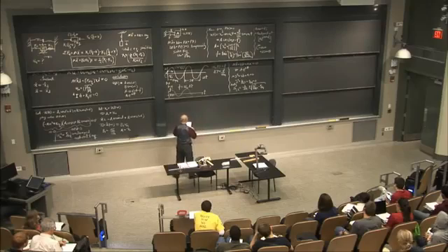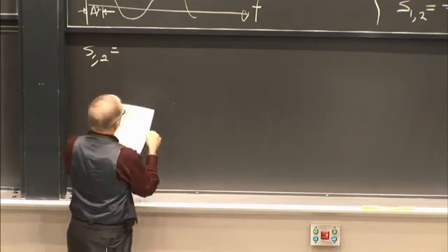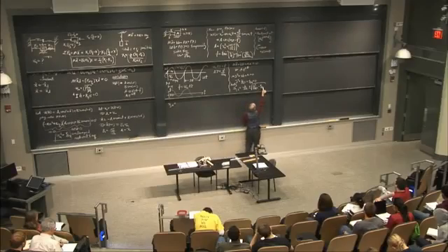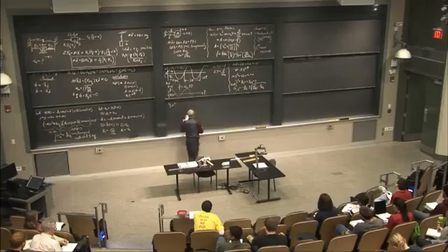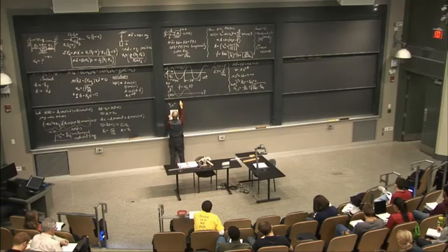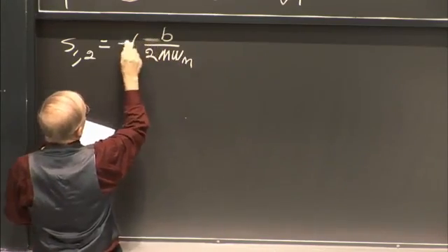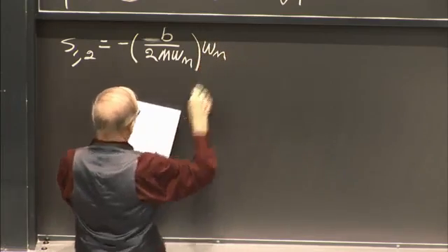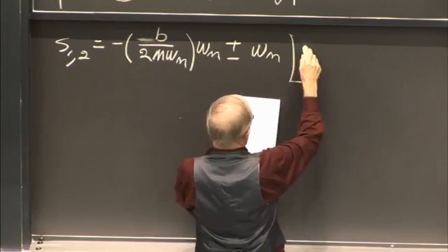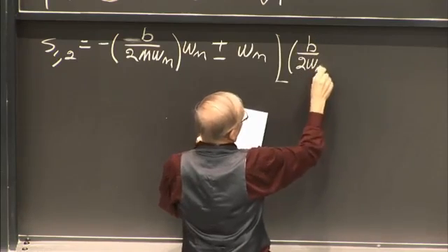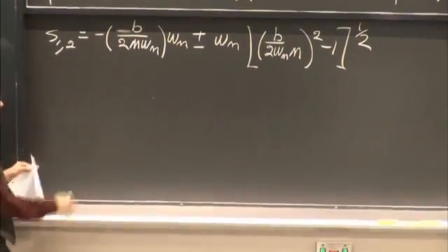And an engineer would say, well, let's change that a little bit. So for the roots I would use for S1 and 2, I factor out omega n squared. I can factor that out and it becomes omega n on the outside, and I put an omega n in the numerator and denominator here as well. So I get roots that look like this. So I've just manipulated that a little bit.